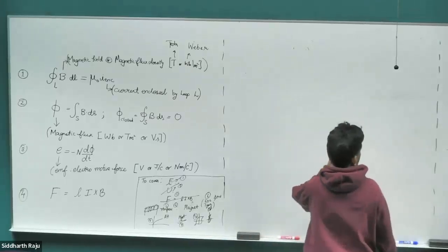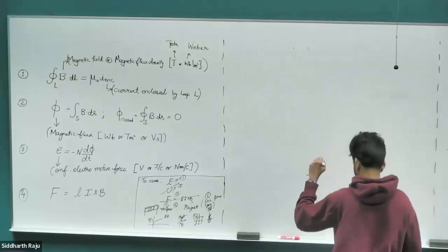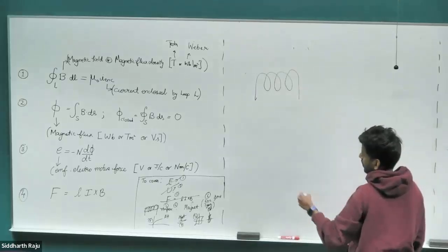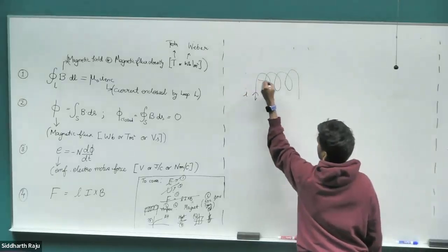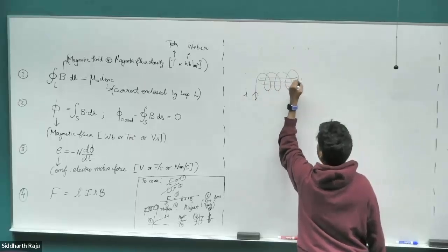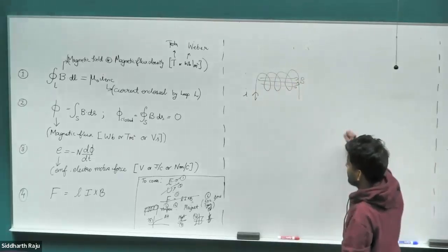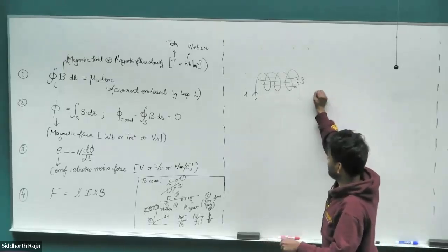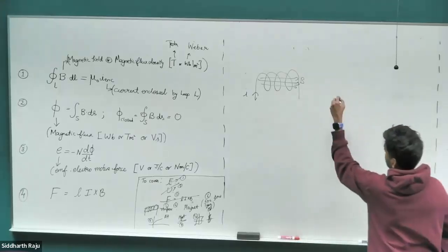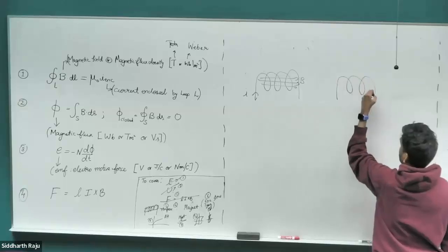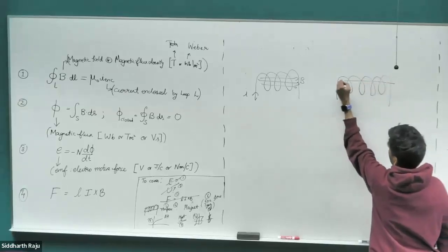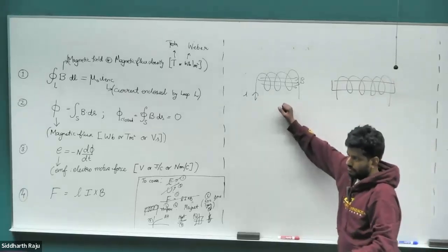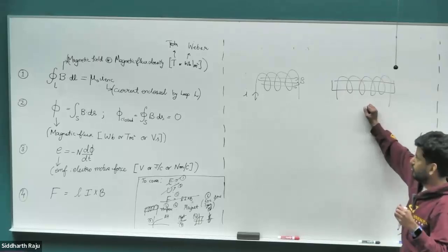So right now we have figured out how a solenoid works. We have some current carrying conductor, and this is going to create some magnetic field. And Ampere did the same experiment where he created a solenoid, passed some current through it, and he observed some magnetic field. And for whatever reason, he wanted to see what would happen if he put an iron bar inside the solenoid, right? So far we have considered an air core solenoid, but now we are going to look at it with a material inside, an iron core solenoid.